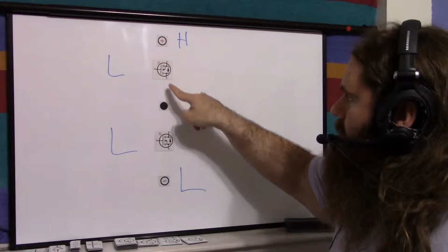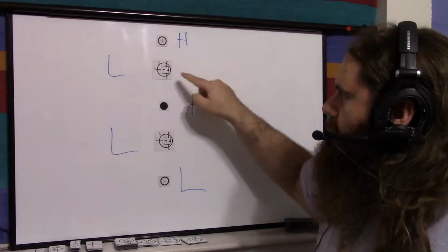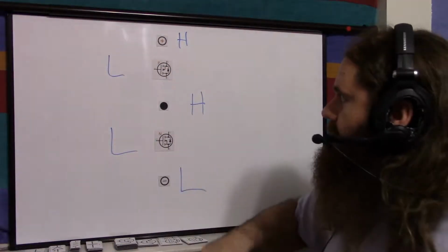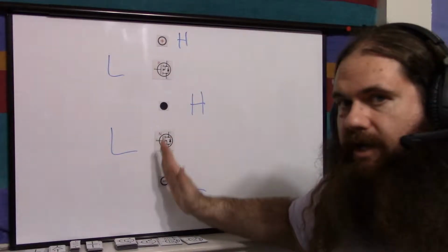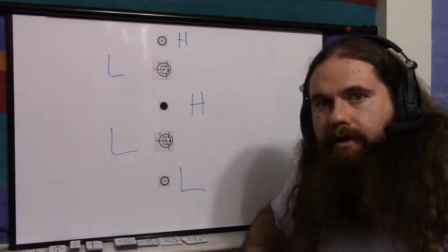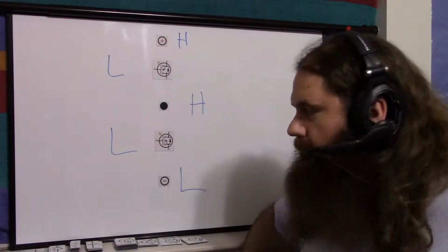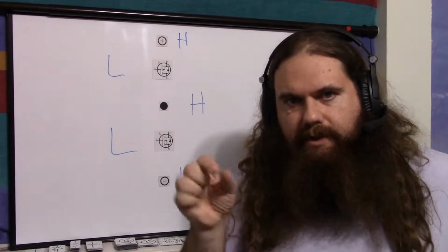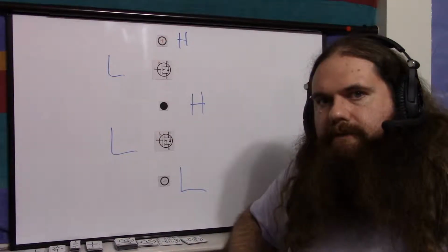The only current going out would be if there were a load here, and the current would be through one or the other of these, either out the P-type or in the N-type. So source to drain here or drain to source there. But nothing through. There's no constant drain in order to get this to happen. There's double the parts cost, more space, more wiring, but lower power. So when you are creating your chip and you're just etching the little pieces out, this is a great thing. That's the beauty of CMOS.